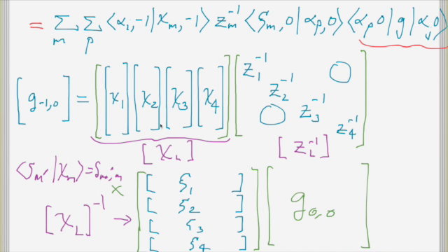So you get the chi matrix, you take your 4 leftward moving chi's, you stack them up as column vectors, create your matrix, take the inverse, you have this diagonal matrix of your propagation factors, you just do that matrix multiplication, and you've related G negative 1, 0 to G 0, 0 in this mode space approach.